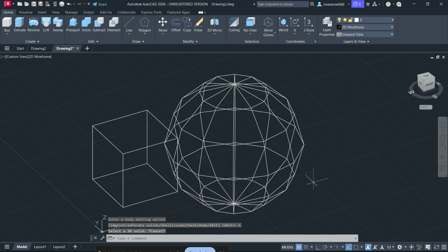If your model contains detailed fillets, chamfers, threads, or other high complexity features, try simplifying it temporarily. Delete or suppress those details before running the union or subtract operation. Sometimes complex geometry creates tiny tolerance problems that prevent the Boolean engine from completing the task. Once the main solid operation works, you can add the detailed features back afterward. This step is especially helpful for mechanical parts, threaded components, and models with many curved edges.